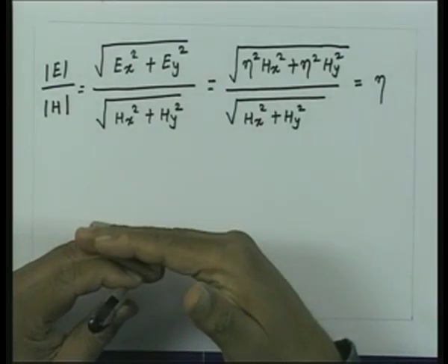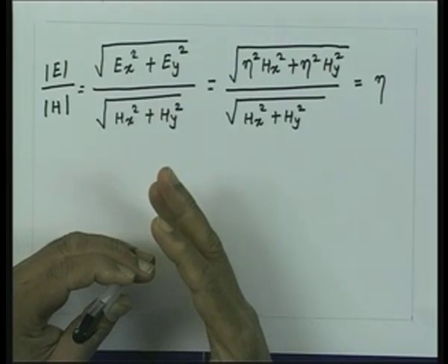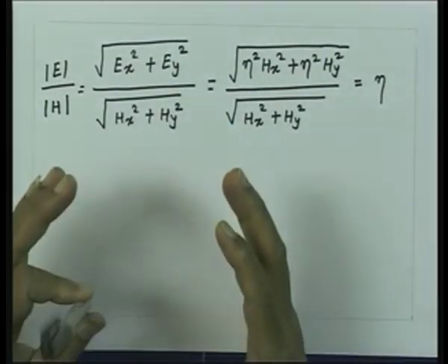So, this transverse electromagnetic uniform plane wave is the simplest solution which you get for the fields in an unbound medium. Precisely that's what was investigated when originally the light propagation was understood, and that's what Maxwell showed by analyzing, that he got the velocity of light correctly by solving this problem and showing that light is a transverse electromagnetic wave.